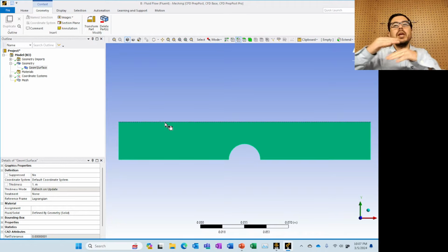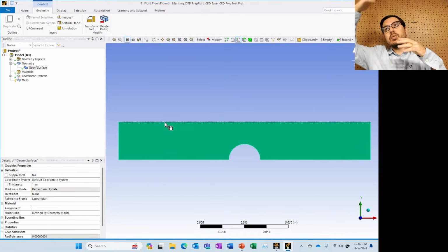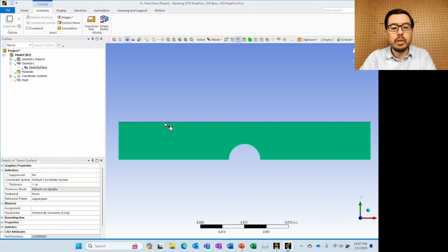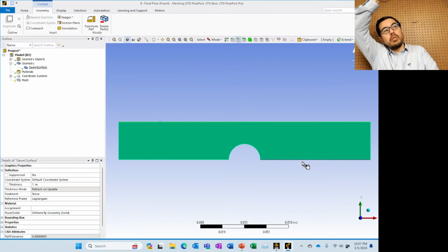And this is going to end up being a mirror boundary condition. So we're going to have a no shear. So we're not going to use no slip. Okay, no slip means that there can be shear there. We're going to use a no shear boundary condition. And so what that means is it's kind of like, oh, there's still just other material above us, and we have kind of a symmetry right there, and so we don't expect to see any slowdown of the liquid on the top. We're going to do that on the top and the bottom. So it's like we're extending our region up and down.